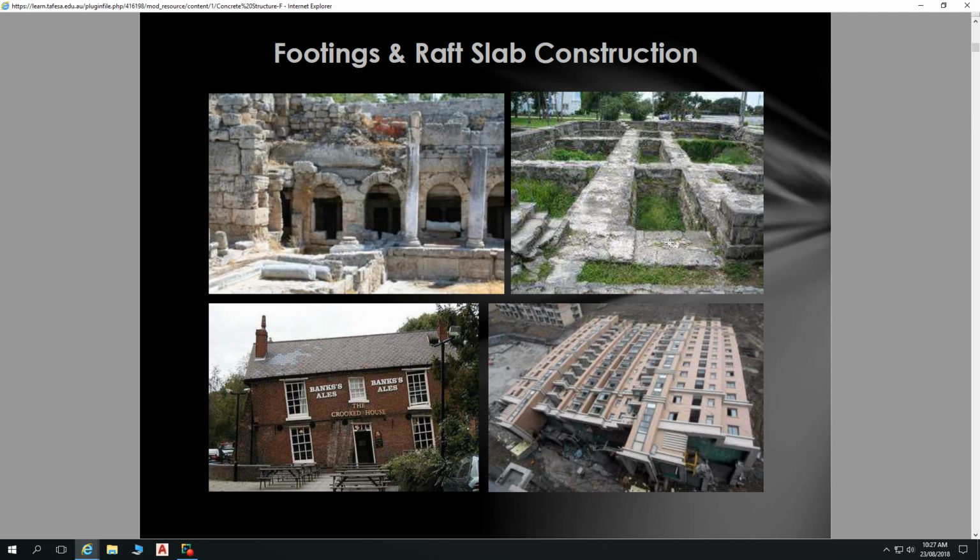So things like adding, instead of steel, adding things like fiberglass, or there's even stuff you might have seen now called polycrete, which is actually really something that's very different to concrete, but it uses much the same sort of concept. So has anybody seen any polycrete stuff before? No one? If you go looking at service pits and things like that, or your Telstra pits and whatnot that are going down, a lot of those are made out of polycrete. I think it's polypropylene, some sort of polymaterial that has sand and has aggregate in it. So it's behaving like concrete, except it's lighter.